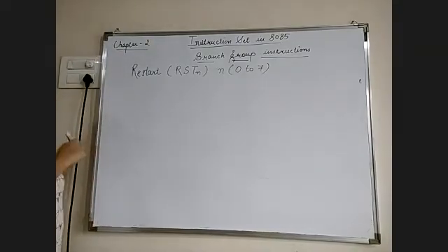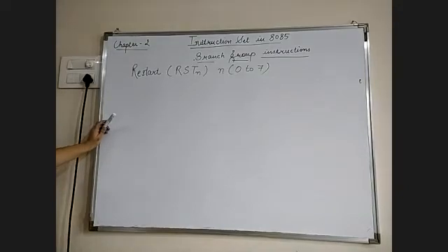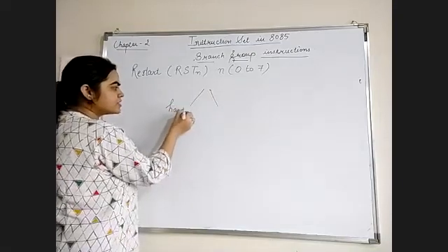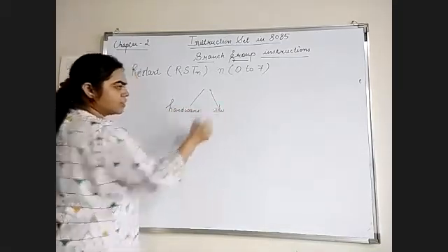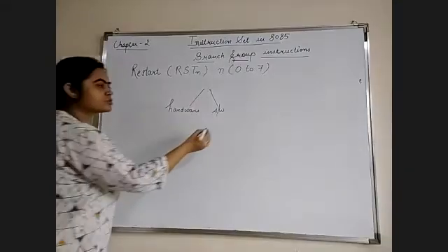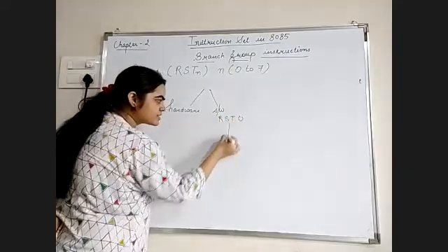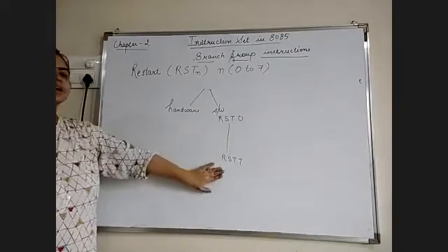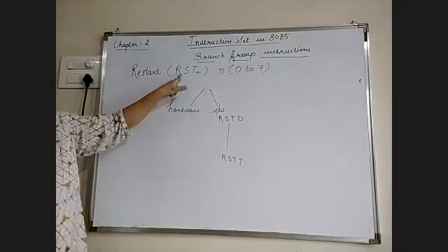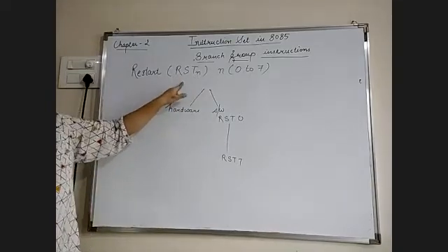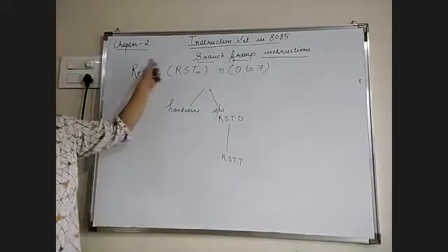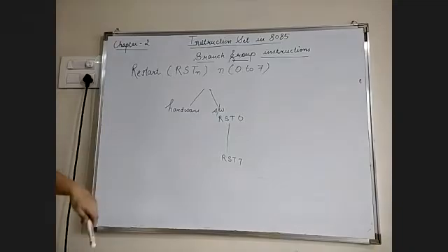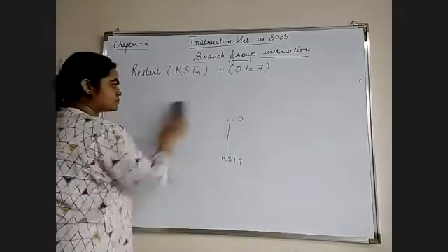Okay. So see here, in case of the restart statement, in 8085 we have 2 different types of interrupts. First one is a hardware interrupt and the second one is a software interrupt. In case of the software interrupts, we have 8 different interrupts that start from RST0 to RST7. So these 8 interrupts are the restart interrupts, that is RST0, RST1, RST2 and up to RST7. So this instruction belongs to the software interrupts, meaning the interrupts which are present in the program itself.